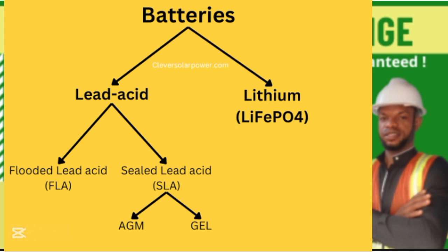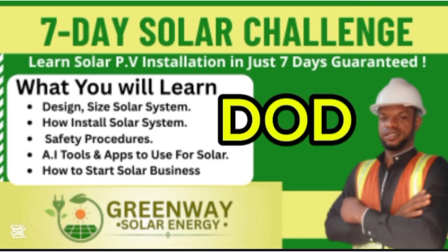Flow batteries can give up to 100%. Do you understand that? So using more than the recommended depth of discharge shortens battery life. We have said that already. Also note that lead acid batteries, for example, should not be regularly discharged past 50%, because it will stress the battery and reduce how long it will last.